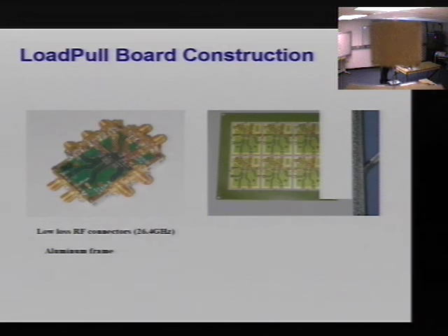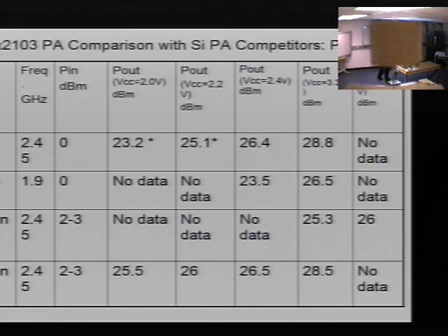You've seen these with a board. I use the G-Tech board, a little bit lower loss tangent. At this frequency, it's probably not as much of a concern. Conductor loss is predominant here. But in any case, it's a similar type of setup with boards and a chip there with external passive components.